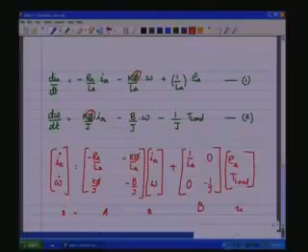Now, if phi is not a shunt, but let us say a series motor, in that case phi itself is a function of IA. So, which means here phi becomes proportional to IA, which results in, let us say this becomes now K1 IA.